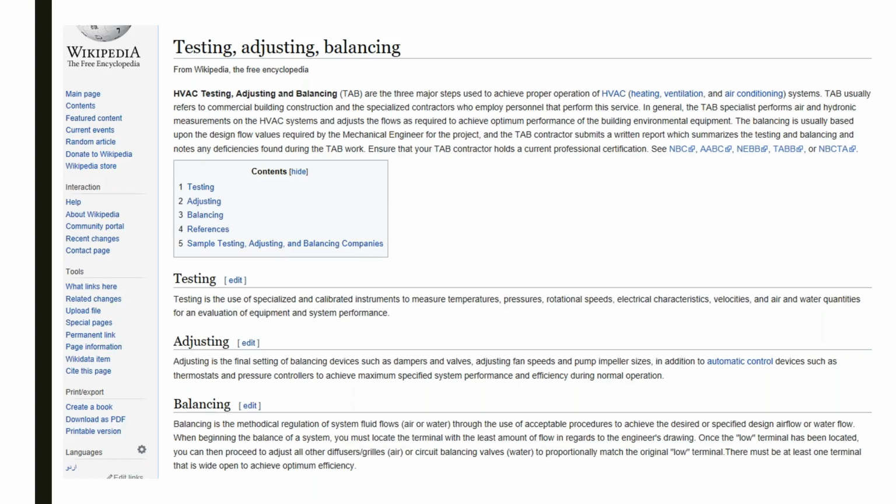Maybe what you should do as part of your PA, you do a little bit of retro commissioning investigation, not a full retro commissioning, but you look at things. Well, that's why I said earlier that the typical process is that you test, look at the results of that as part of your RCX. You didn't adjust anything. You just tested to see where do we stand today. And then you make your recommendations, and then you go back and adjust and balance after that. So you're breaking it apart. Whereas new construction, test, adjust, balance, boom, boom, boom. Go. There's no analysis in between.